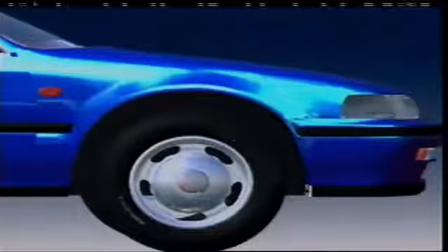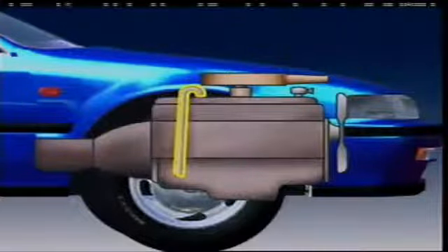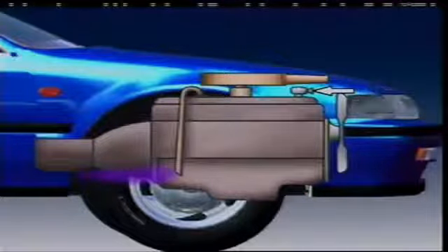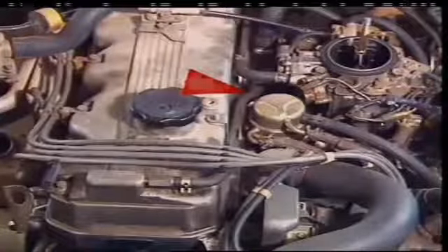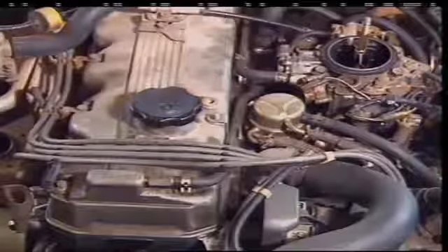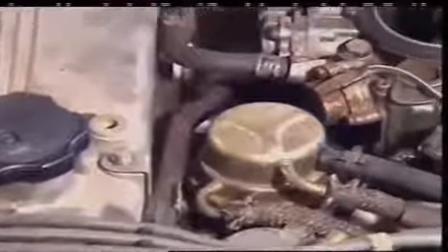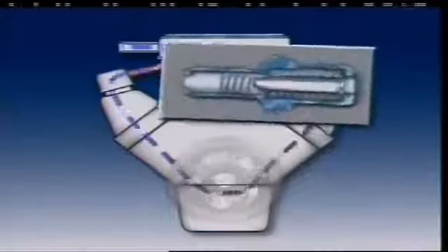In older vehicles, crankcase vapors were vented directly to the atmosphere through a breather tube or road draft tube. It was shaped to help draw the vapors from the crankcase as the vehicle was being driven. Modern vehicles are required to direct crankcase breather gases and vapors back into the inlet system to be burned. A common method of doing this is called positive crankcase ventilation, or PCV. A valve called a PCV valve regulates gas flow between the crankcase and the inlet manifold. It is controlled by the pressure in the manifold.